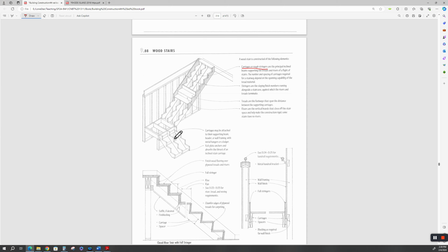Carriages, they're a hanger board for these stringers. You're going to want carrier boards up there. You'll want a carrier header or board here, and you don't give this to the junior carpenter to cut, to lay these out. These all have to be uniform and evenly done. It's done with frame and square. And if you're interested in how to actually cut these things, get on YouTube. Larry Hahn's got a good one. The reference back to that other article with the Rhode Island. He's got a side link where he's laying stringers out.